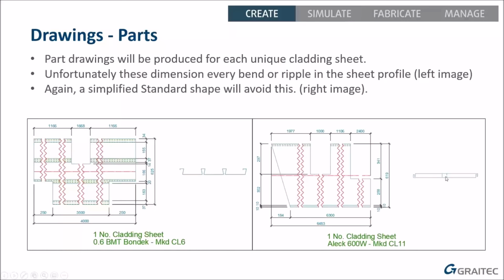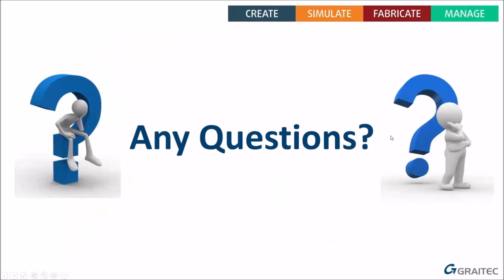Most sheets, the bottom interlock and the top interlock are actually different, so it might be quite obvious. But this one looks like I could turn it over and it would be the same either way. But of course it's important to get the right front, so that is a slight hiccup. You might have to think about that. But that's a neater drawing because it's only dimensioning the cutouts, not all the irrelevant ridges that are already made.